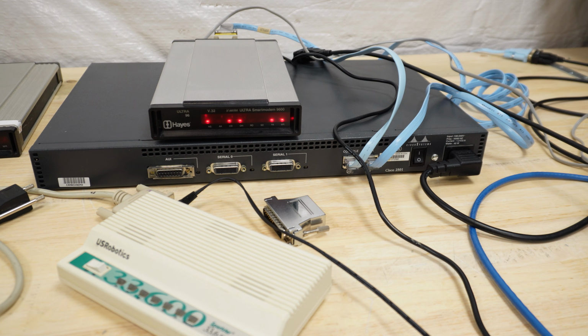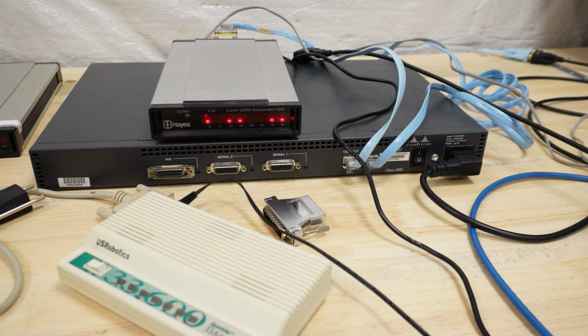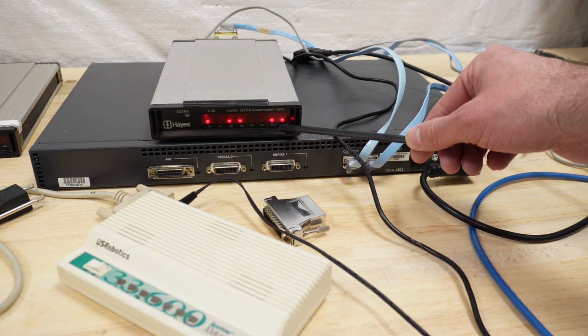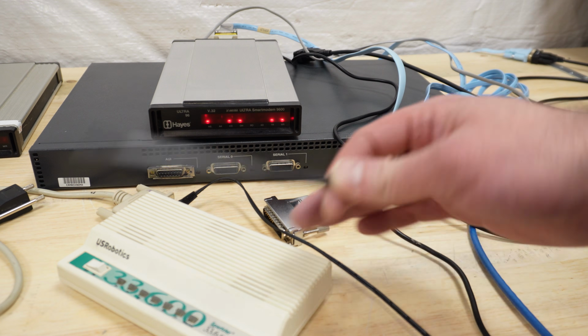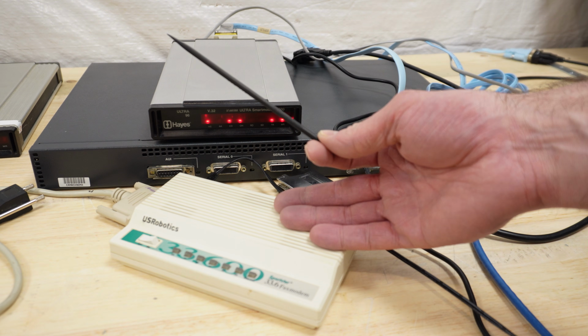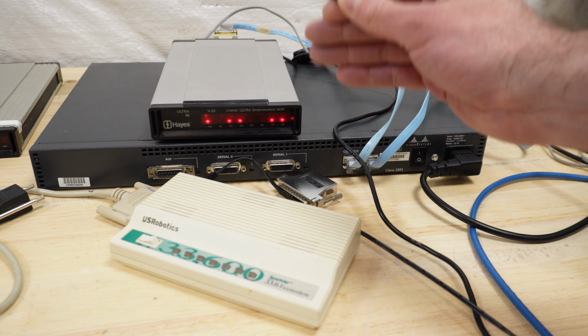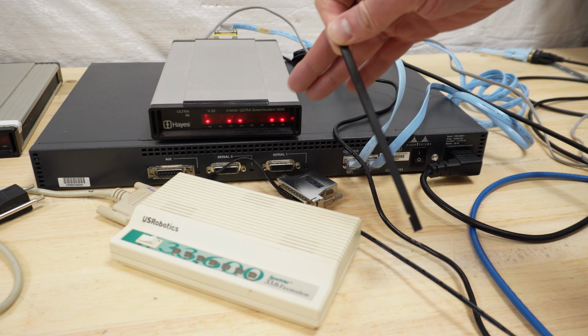It's 2 hours later, and my will is weak. Stamina is low. But as you can see, we've got some good lights here. Carrier detect, terminal ready, read and send are not blinking away. I messed around with these for 2 hours straight, hooking them up over the serial port. I could get both of them to behave the same and almost work. I found that if I took flow control to software on this one, they would stop blinking, but I don't think that's how this is going to work.